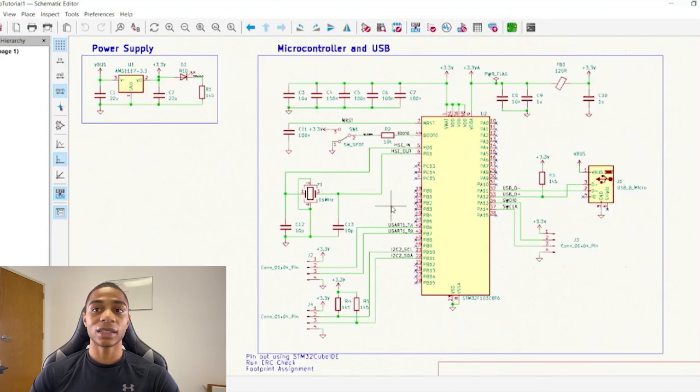And if we talk about what exactly a bootloader is, it's responsible for placing our operating system into the main memory of our processor. So when BOOT0 is low, the operating system that will be placed into our processor is the original operating system. But when BOOT0 is high, we have the opportunity to change that and boot from maybe a different OS or a different firmware.